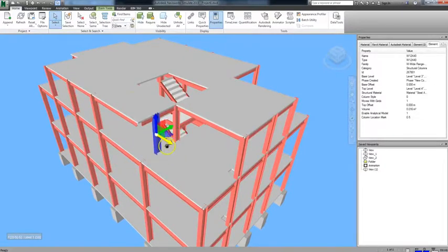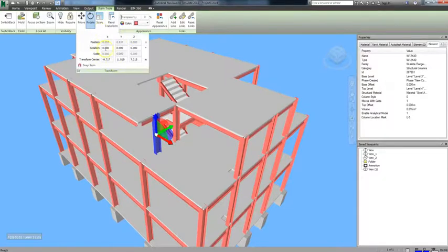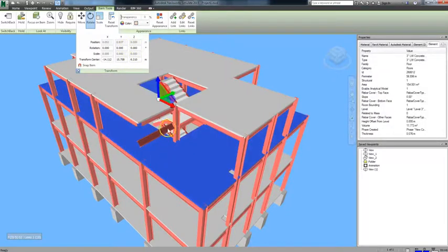You can also choose to rotate items from the Item Tools panel. Just like with moving the item, you can use the gizmo to visually rotate your item, or you can enter the value that you want it rotated in degrees along the X, Y, and Z axes. Again, you have to choose between convenience and accuracy, and only you can decide what will be best for your project.